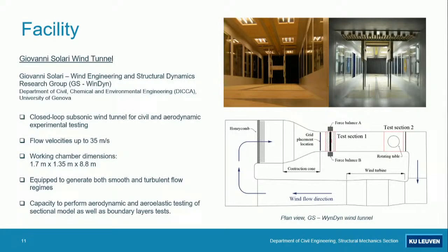So the wind tunnel has already been introduced in some of the previous presentations, so I'll limit myself here to indicating the section of the wind tunnel where this test was performed. So previously the tests on the building were performed here at the rotating table. Here we are closer to the contraction cone, and the test section was actually fitted in between 2 force balances that allowed us to measure drag, lift, and moments.